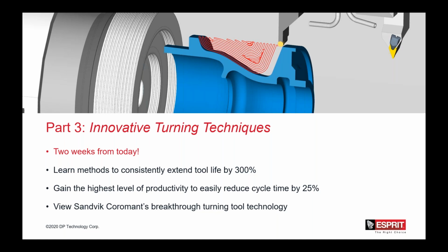Yes, I think I mentioned that our pilot drills have a different point angle. We have a flatter 150 on the pilot and a steeper 140 on the deep hole, so that the deep hole drill that follows the pilot hits in the center versus the outer corners and helps it center better and track straighter, if that answers the question.